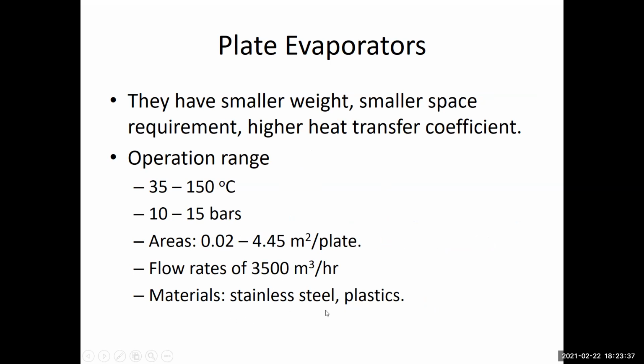Stainless steel, to fight scaling, is a very good choice, but it has a problem that it comes with high cost. Plastics are there, and this is something new that people are testing now. There's no issue of corrosion, but the heat transfer characteristics are a little bit less, and that's why they try to use some sort of, I would say, plastic alloys so that they can compensate for the low heat transfer coefficient.